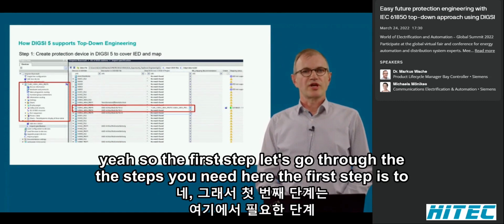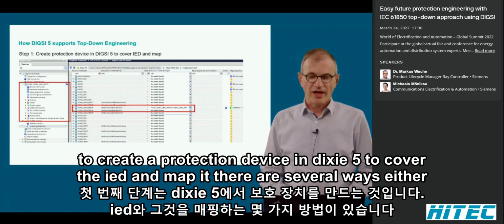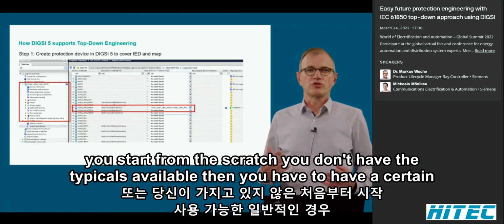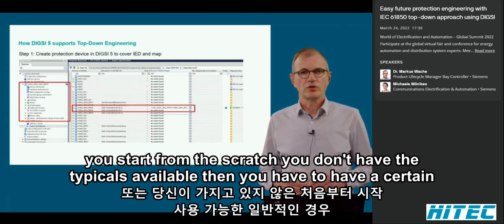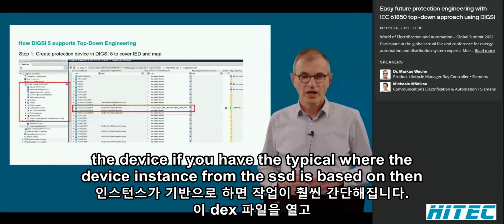So the first step, let's go through the steps you need here. The first step is to create a protection device in DIGSI 5 to cover the IED and map it. There are several ways. Either you start from scratch, you don't have the typicals available, then you have to have a certain knowledge about the required protection functions. On the left side, you then choose on your own the device.